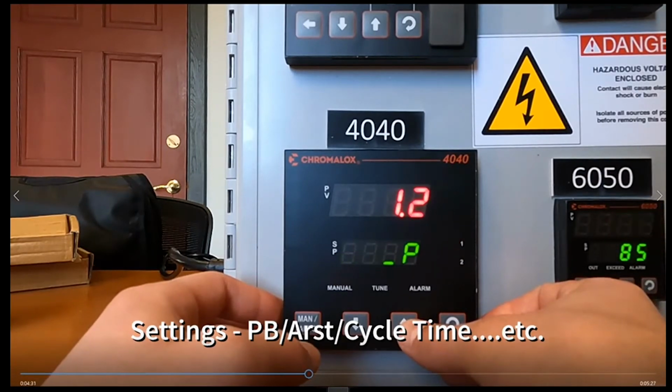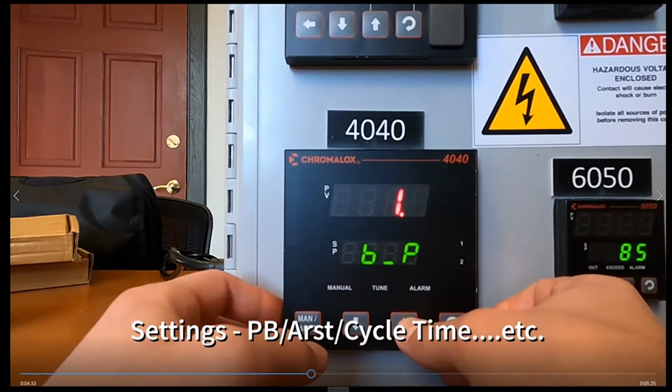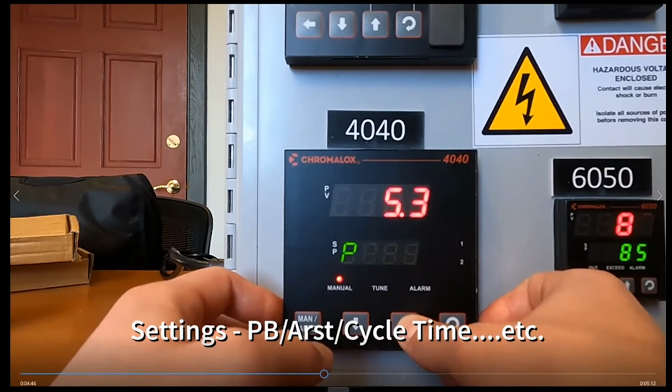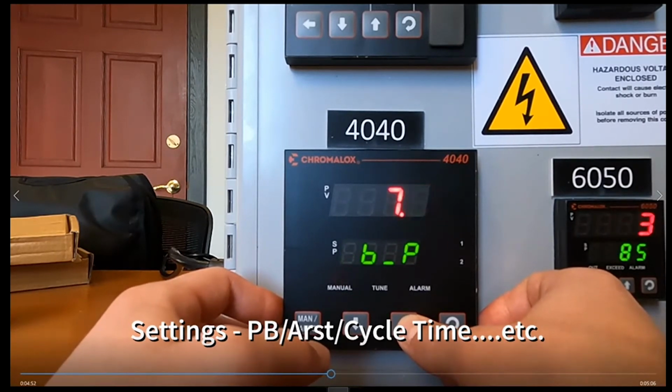So in this particular case, what percent of 1,000 do we want the proportional band to really start kicking in? I forget what I set this to exactly. I think it was like 10. So it would be 10% of 1,000, so as soon as you're within 100 Fahrenheit of your set point, the P portion of the PID control will really be kicking in.